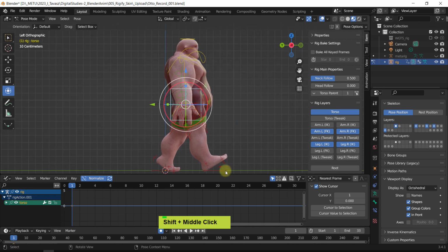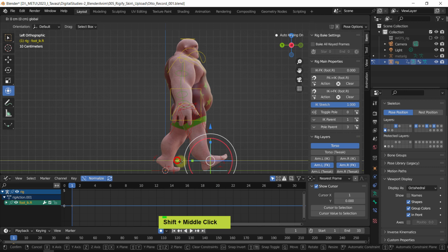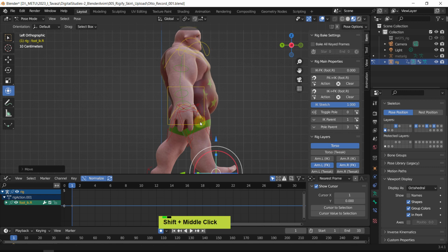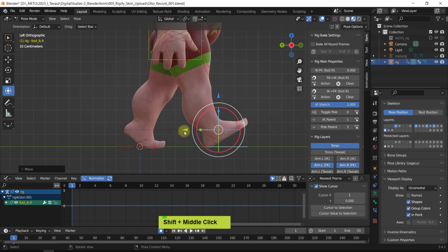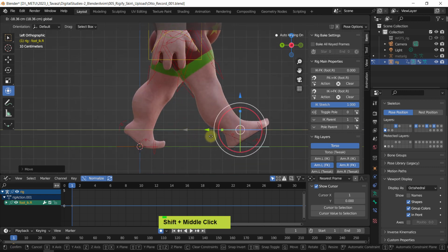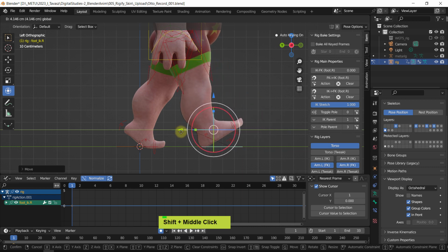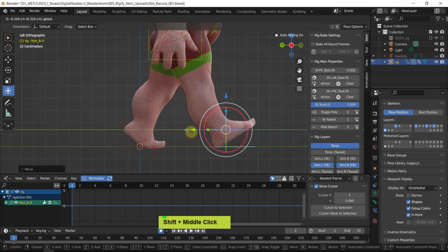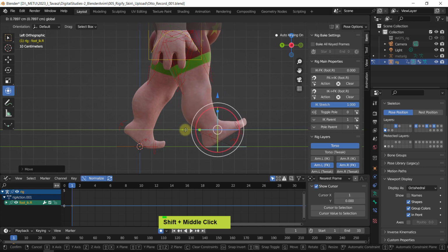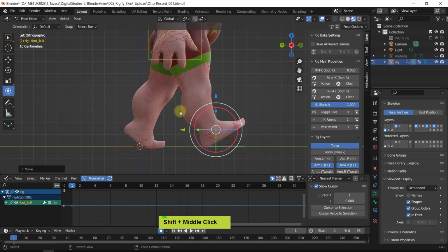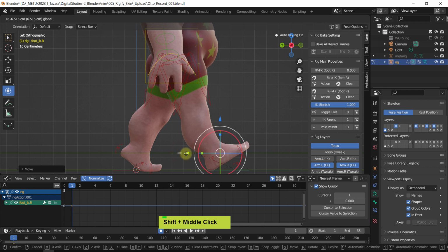Looks great. Maybe if I can move it forward. Yep, but okay, so if I'm moving forward, can you see the knee? If I move forward too much, it starts stretching. If I'm moving it back, you will see a point where it starts actually bending. If you don't want the knees to pop all the time, you want to try to maintain that range of motion, so you're not reaching out too much, and this can generate a somewhat natural movement.